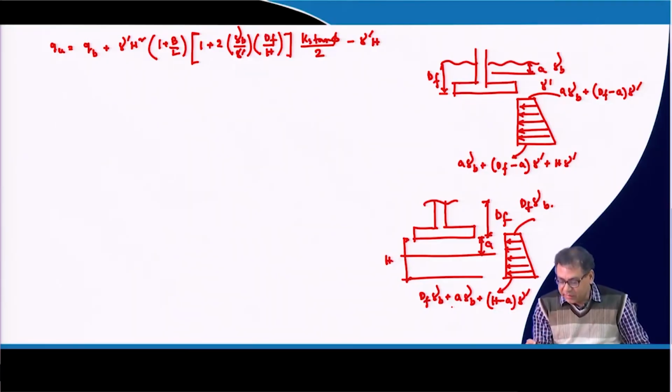And remember, do not always use this equation for the water table case, because we have to modify the equation and calculate this area depending upon the position of the water table. Depending upon the condition, you have to modify this, because in our example problem the water table is at the base of the foundation. So, I can use this equation, remember, very clear.